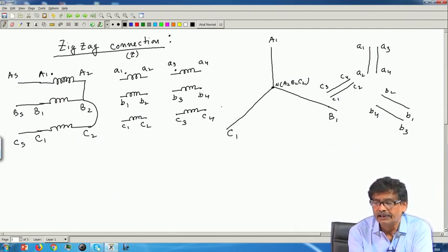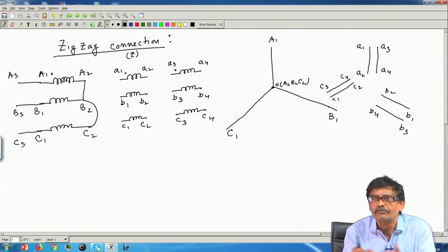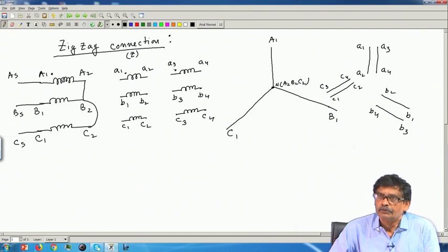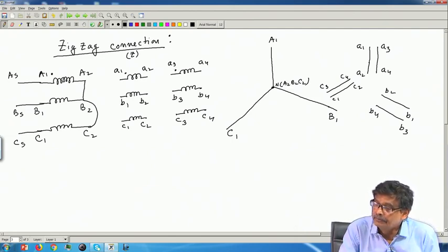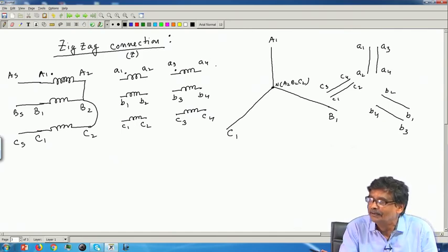That is, you do not connect A1, A2 and A3, A4 in series, there will be mixing of phases. So, these voltages are this one A1, A2, of course, you can connect them in series, then it will be effectively a single coil of 2 N2 turns.